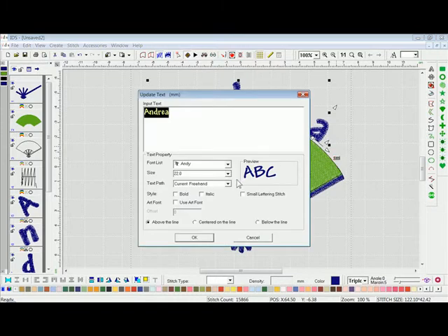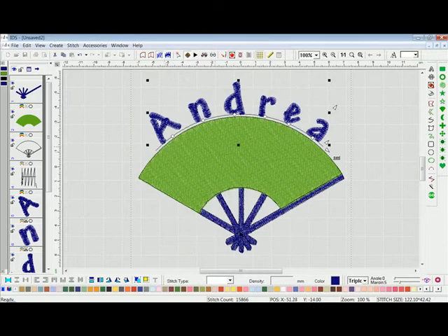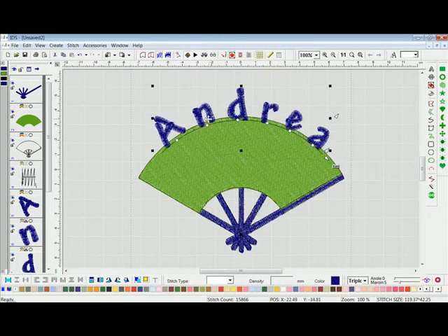We'll go ahead and hit edit. We'll change it from current freehand to existing outline, and change that to a -2 instead of a +2. We'll press OK, and again we'll start here with a left click. You have to make sure that you're exactly on that baseline. Left click for your other endpoint. When it's blue, I left click and it sits inside that area 2 millimeters. So you can see that it's sitting negatively.